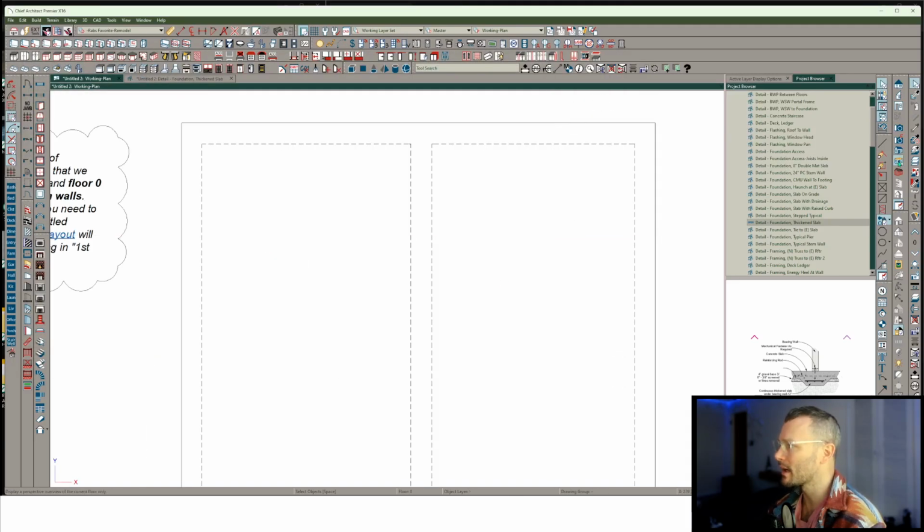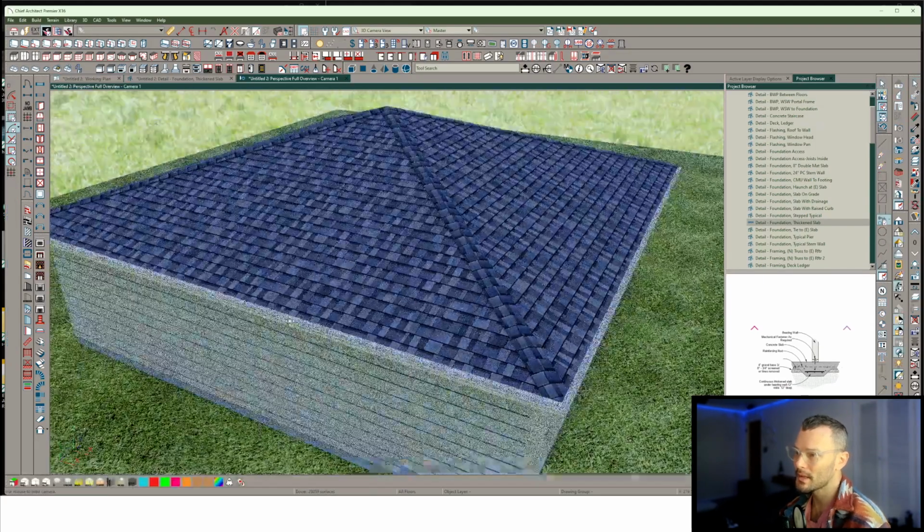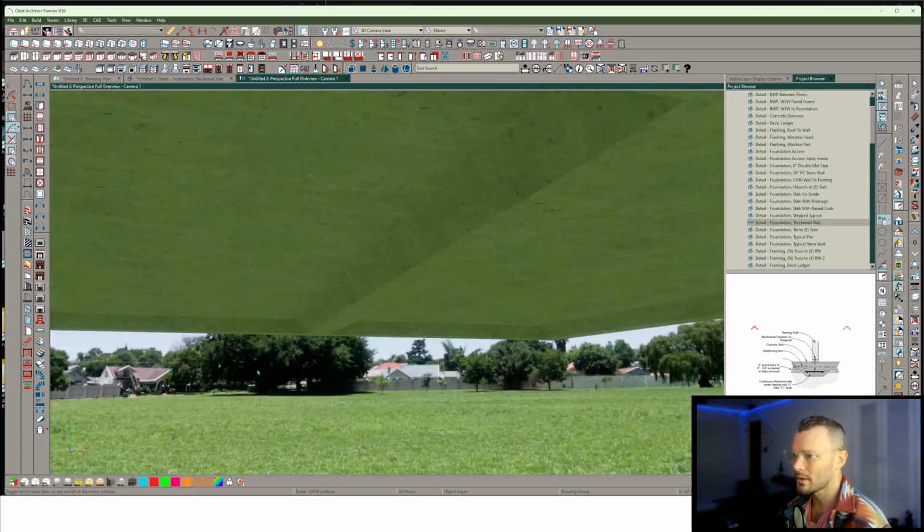Let me say OK. And let me just pull, you can see here, it built a footing. And let me pull a 3D camera view, and we'll just pan this camera underneath the building so that we can see, and we'll just do a line over method here. There we go. It built that intermediate chamfer continuous thickened slab at that bearing section.